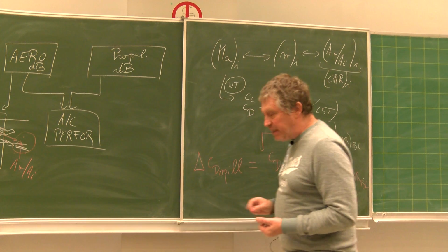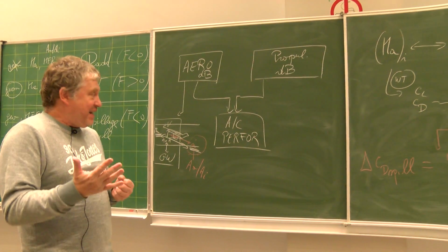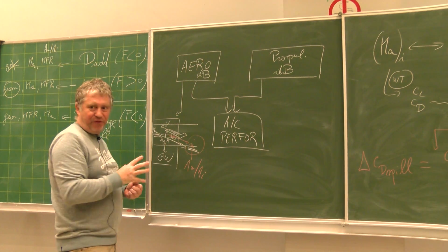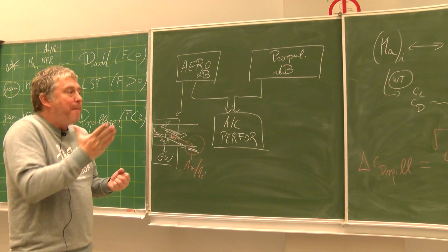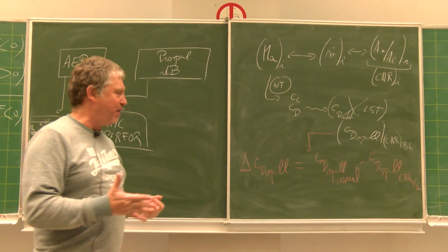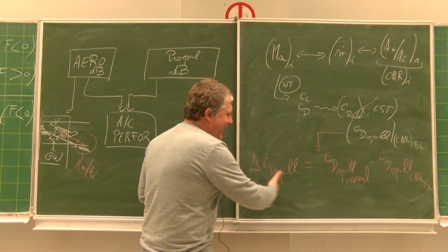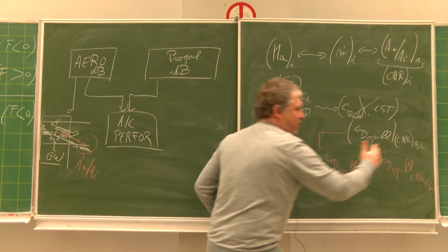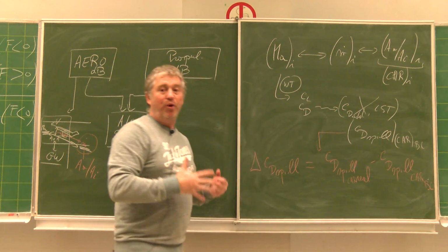So they need to understand, for each Mach number, the influence of the other values of AA divided by AI compared with the capture area ratio baseline that you have defined. So you need a delta CD spillage that considers the value already included in your force computations with the real one.